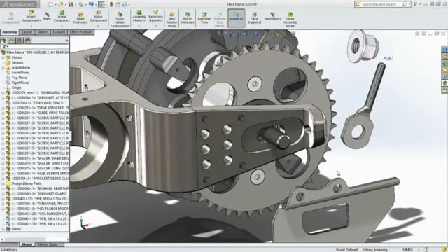One of the things that positions SolidWorks software so far above the competition is the broad array of mates that are available. Mates create geometric relationships between assembly components. As you add mates, you define the allowable directions of linear or rotational motion of the components. You can move a component within its degrees of freedom, visualizing the assembly's behavior.